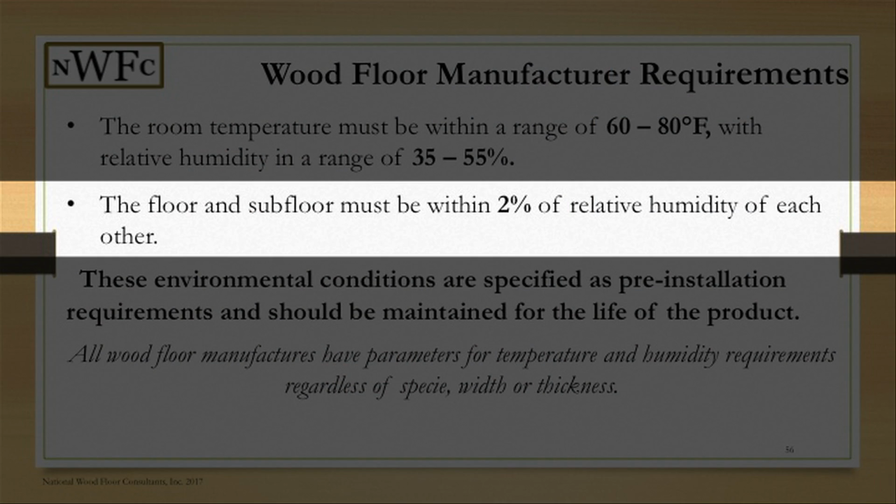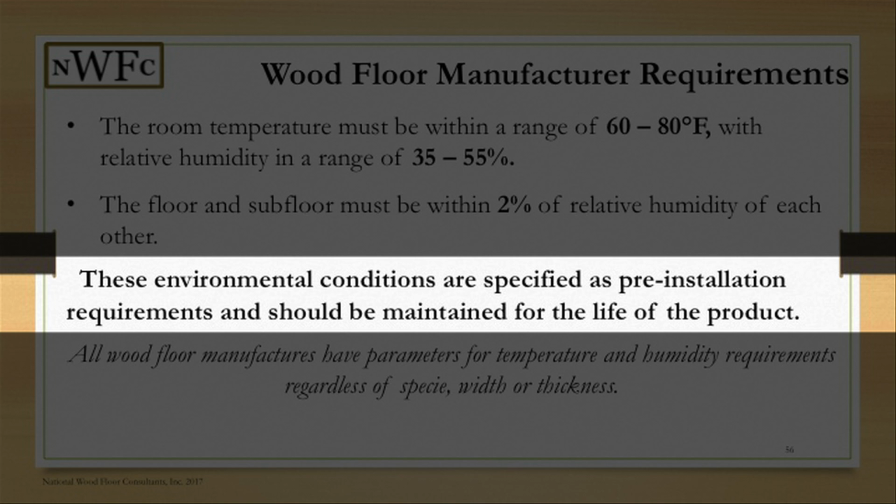Then you look at the substrate. Between the floor and the substrate, they must be within 2% relative humidity of each other. But when you look at the environmental conditions and the specifications of your pre-installation, the requirements should be maintained for the life of the product.